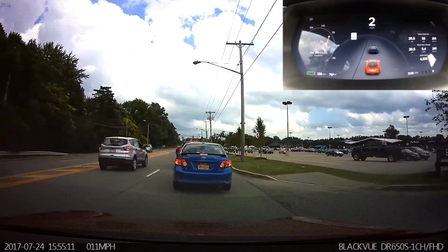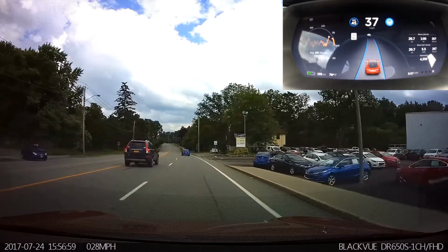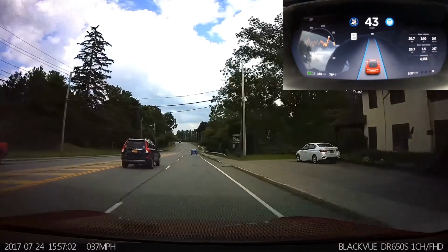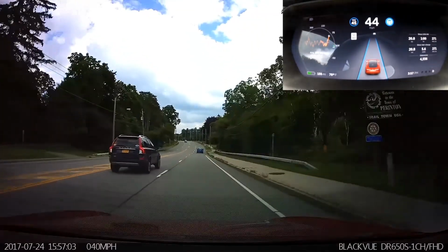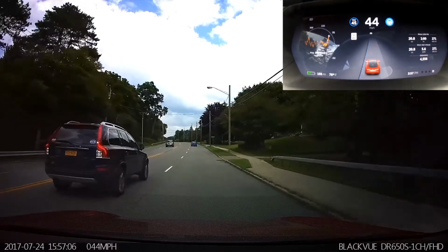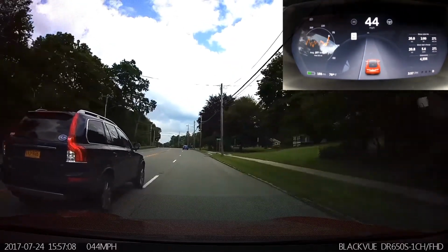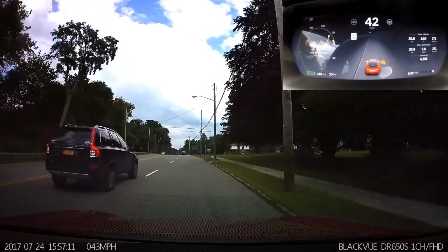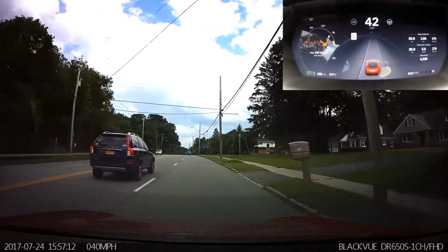Very inconsistent. This video is going at 3/4 speed. Watch the car in the left lane. Auto steer thinks it has both lane markers coming up. They're about to disappear. The car on the left isn't seen by auto steer. The lane disappears. The car moves over to the left. The other car is moving over to the right. If I hadn't turned off auto steer, we would have collided.